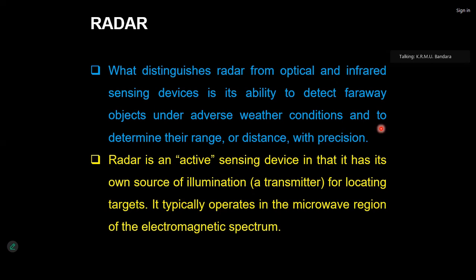This is the same as a total station in surveying. You can send the beam to the target, and the reflected one is detected by the total station, which calculates the time difference between sending and receiving, and then calculates the distance. In addition to the distance, the total station calculates the bearing of the line, so it can calculate the two-dimensional coordinates of the target, especially the three-dimensional coordinates. The same thing applies here.